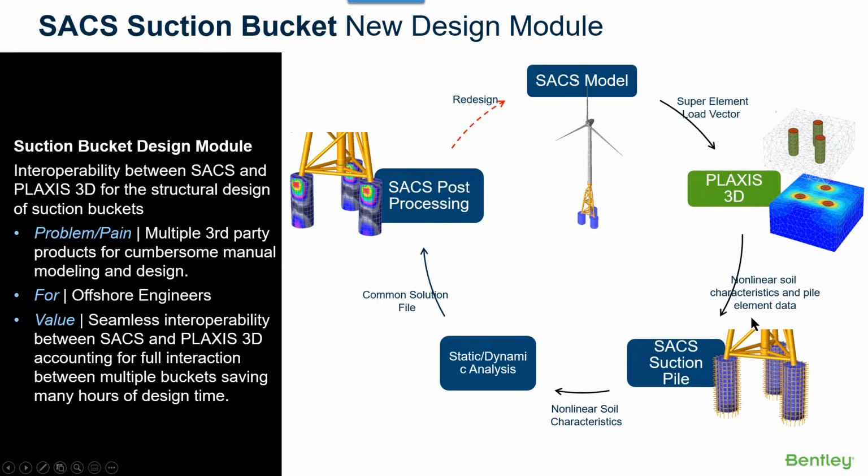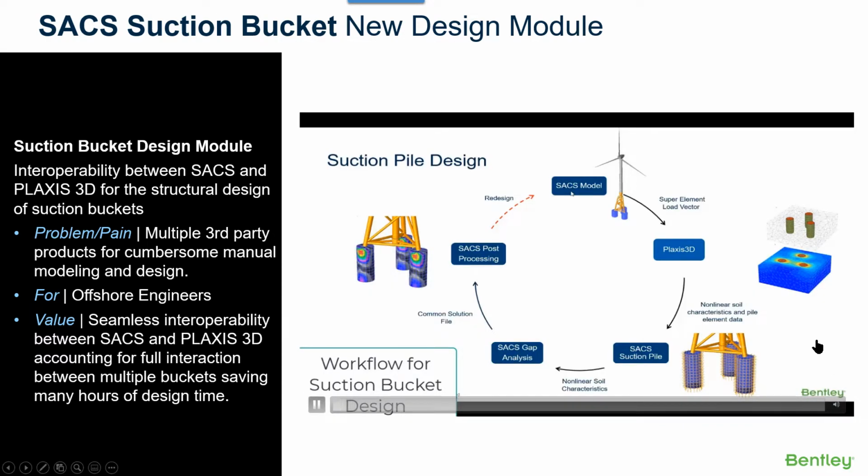After importing a set of nonlinear springs, we can perform any dynamic or static analysis to evaluate the structural stability of the entire structure, including the suction bucket. Let's watch the video. Here's the workflow I explained in the previous slide. After calculating the nonlinear springs, SACS imports them and runs the structural analysis.